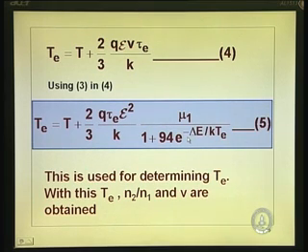So, all that we have done is we have used that electron temperature, and that unknown quantity can be found out from this equation. Tau e is a relaxation time, known, E is the electric field that you are talking of. What you are trying to find out now is, with the electric field, how hot the electron becomes. You have got T on both sides. It is a transcendental equation. So, you have to solve it numerically finally.